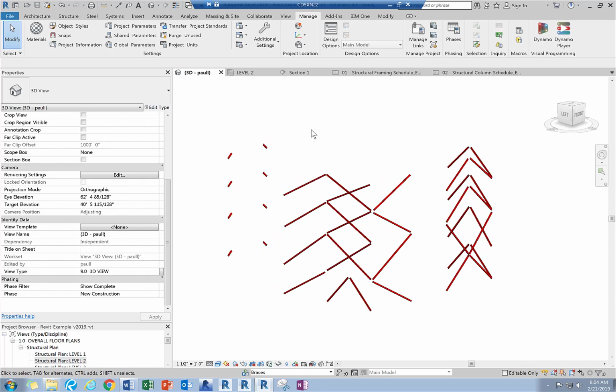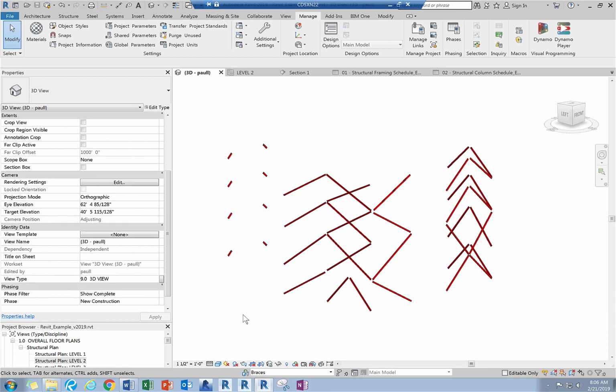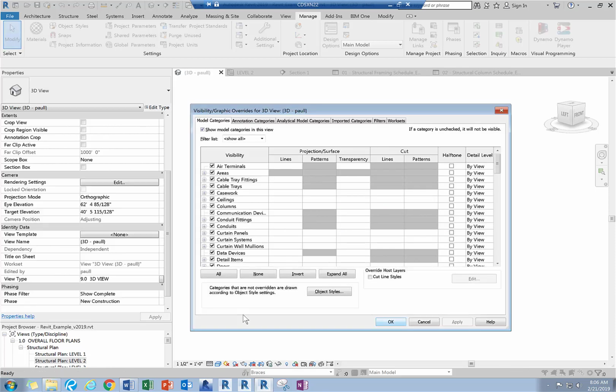These are all the braces that are assigned to the braces workset. Notice that the knee braces are assigned to the braces workset and that they all receive the number 0 in the intersecting levels parameter. Now that we have our geometry assigned to the appropriate worksets, it is time to show you how to export your model using Dynamo.